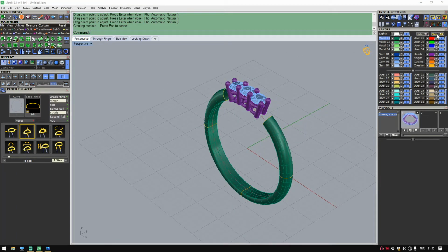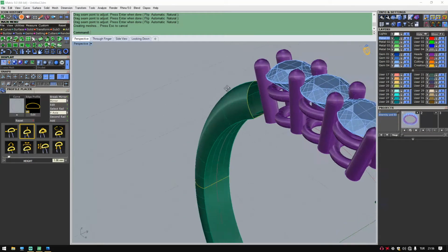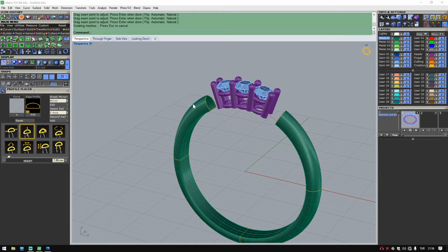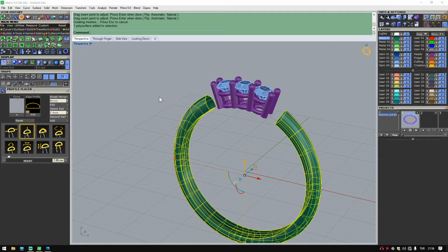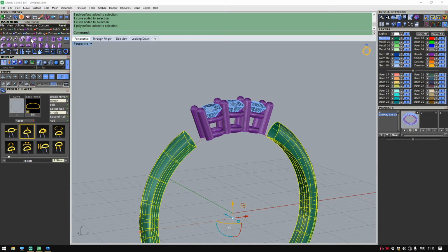Before showing the hidden gemstones, as you can see this is open, this is hollow inside, it's just the surface. We need to create this to make a poly surface. We need to close the ends and it will be ready for printing then. You will need to select the surface, and then go solid and use this one, cap planar. This command is basically capping the hollow ends.